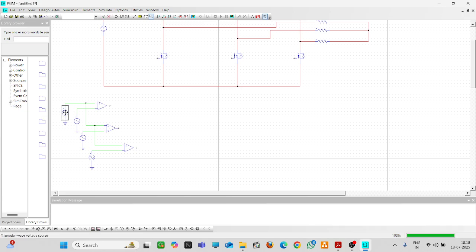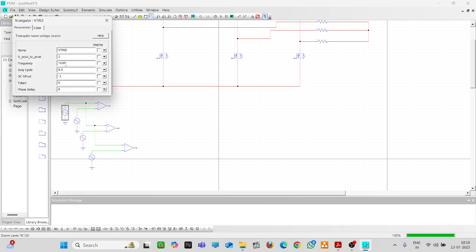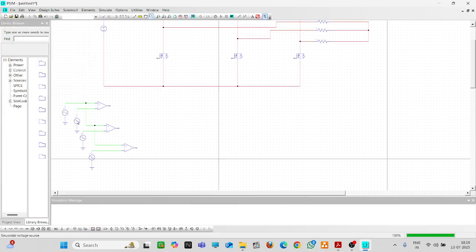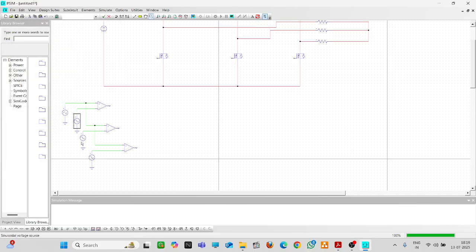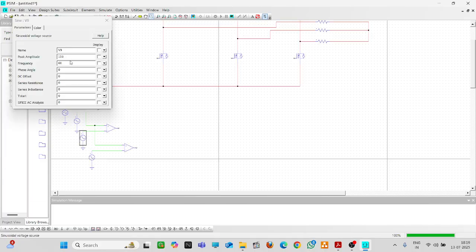Now the frequency has to be kept fixed, that is 1000 with peak to peak. So you will be having a waveform from +1 to -1. We have kept the carrier frequency as 1 kilohertz. Now this is the reference waveform. This should be 1. Then I'll make it 0.8 because you can vary the amplitude of the reference signal from 0 to 1.